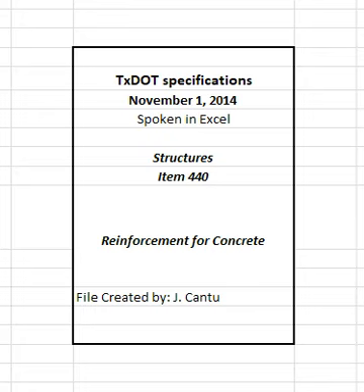Table 5. Minimum inside diameter of bar bends. See table in specifications. Bend test representative specimens as described for smaller bars in the applicable ASTM specification where bending number 14 or number 18 grade 60 bars is required. Make the required 90 degree bend around a pin with a diameter of 10 times the nominal diameter of the bar.